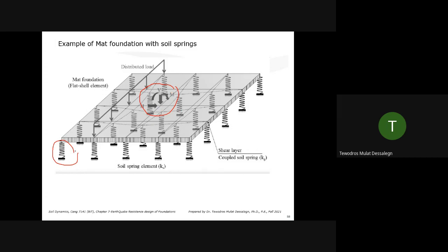The mat is then put on elastic springs, and you can analyze this in programs like STAAD.Pro or SAP. Springs can be modeled, and this plate can be modeled, and you can find your shear forces, moments, and punching shear, whatever it is in the panel. So this is like a geotechnical foundation. You can analyze it with springs.